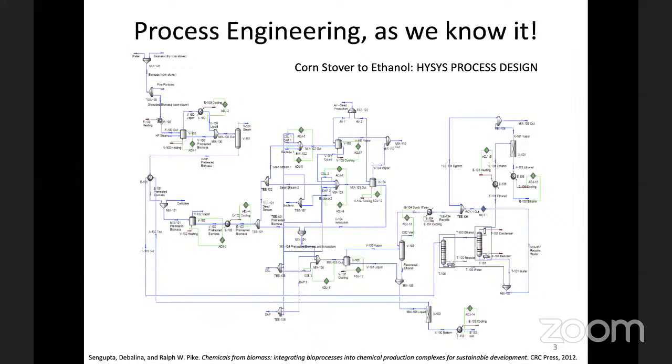There has been research done on many different kinds of ethanol in fuel blends, and I'm going to go into that. But corn stover to ethanol is a process, and ethanol can be made from corn stover through this schematic of first a steam hydrolysis, then an enzymatic hydrolysis, and then going into your reaction scheme and then a separation scheme to get to the ethanol. Okay, so let us keep this in mind.